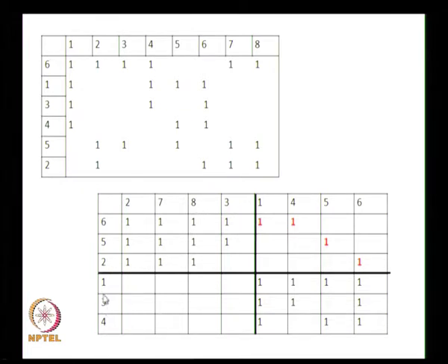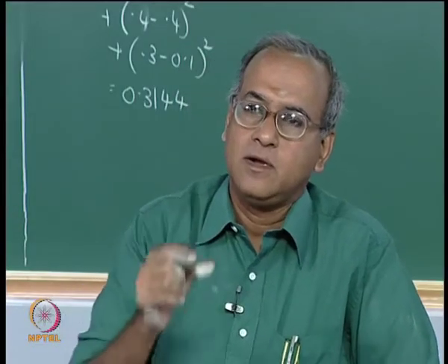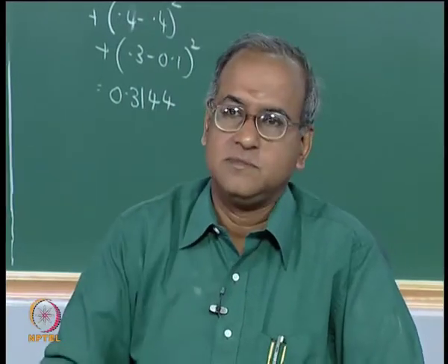This will have machines 1, 3, 4 and 6, which is duplicated. The parts will be 1, 4, 5 and 6, but these 2, part 5 machine 5 and part 6 machine 2, will be subcontracted, operation subcontracting, and there will be no intercell move. Now, in terms of cost, part subcontracting will be costlier than operation subcontracting.